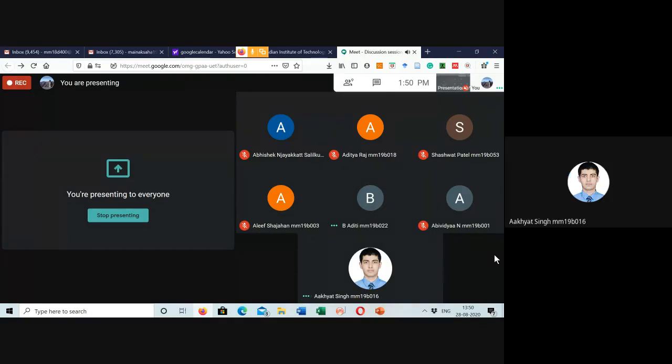So can you just show it? I guess there'll be like 2 for the slip direction 111, if you take the body. That's what I'm saying. So how many slip systems do you have in BCC now? If the top body, then the bottom part, how much? 12, right? 6 into 2, right?